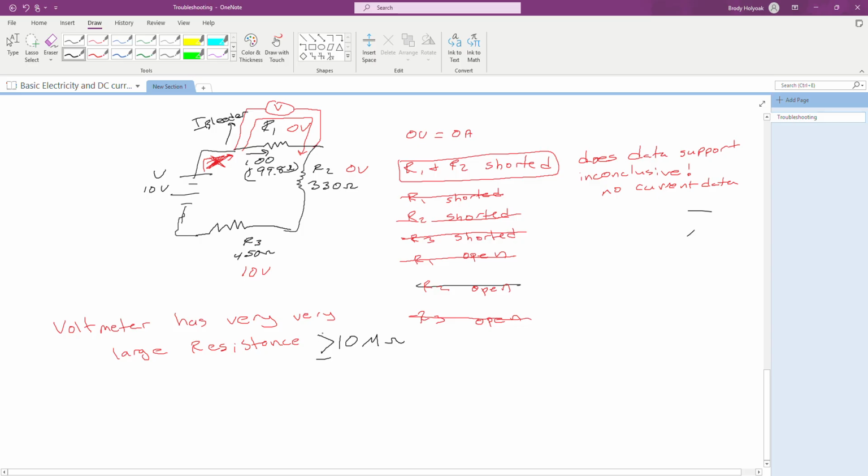With that being said, because this meter has resistance, we now created a closed loop, a circuit or current path. Now when we go to measure this, I've got a 10 mega ohm resistor connected from here. This R1, we'd said, had gone away because we're assuming it was open. Now I plug my meter into that position to measure it. The current is then going to have a path through the 10 meg, through this teeny tiny 330, through this teeny tiny 450, and back to the 10.